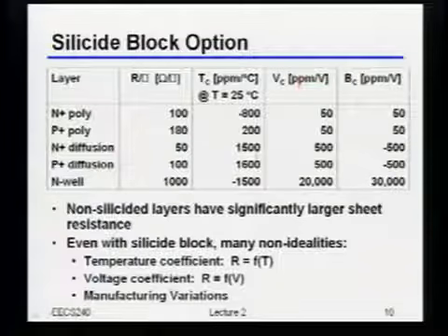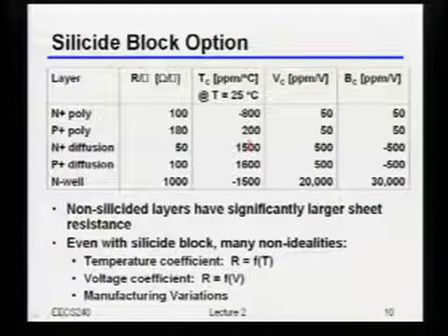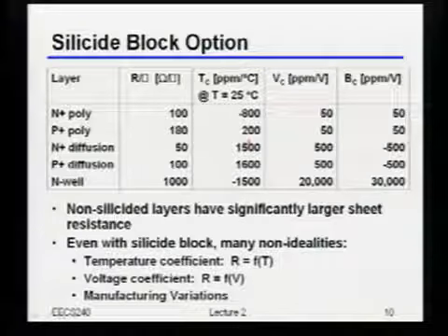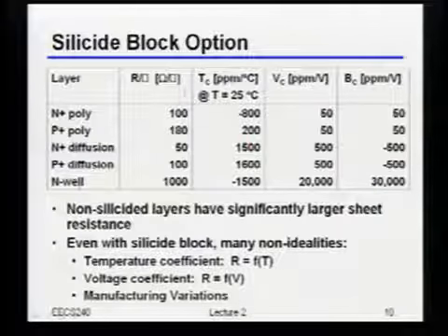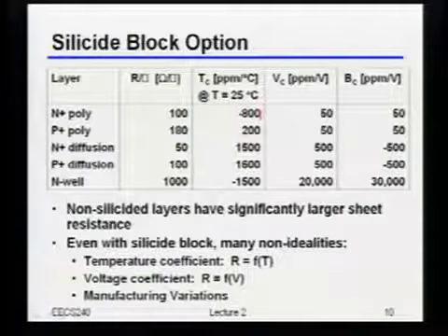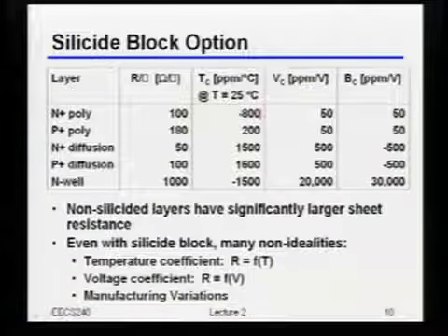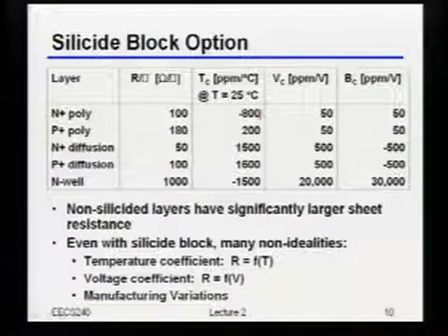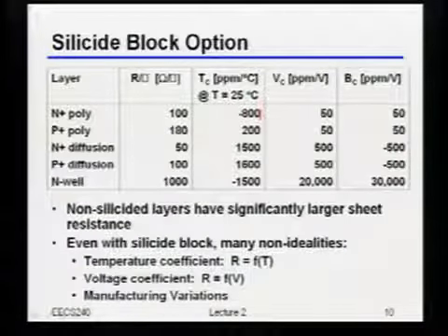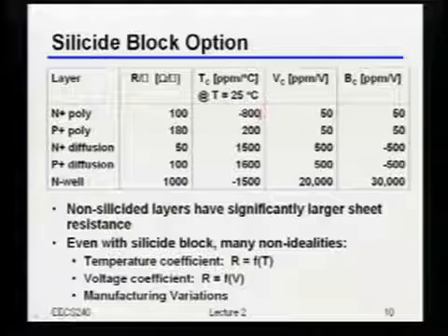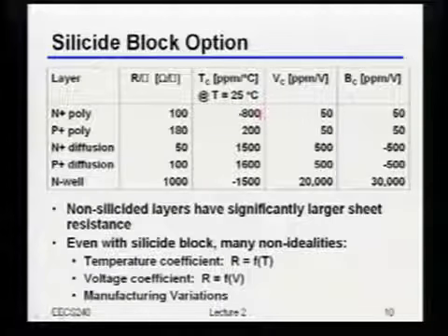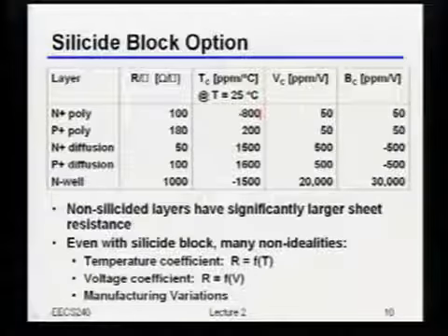So for most of them, as you expect, you make it hotter, resistance goes up. Well, some of these, like the N plus poly and the NWell, their resistance actually goes down as you increase the temperature. Okay, it just has to do with ionization of carriers and things like that. Go bug one of the physics guys. I don't even know. Bottom line, that's what happens. Okay?